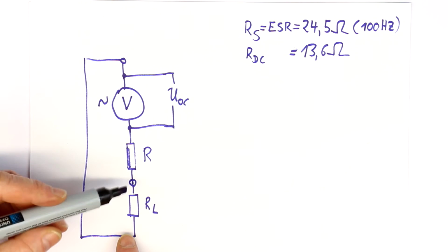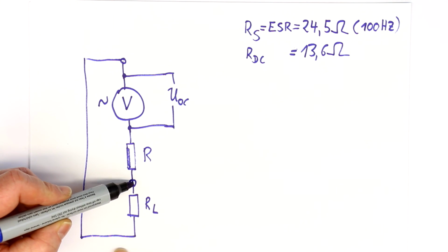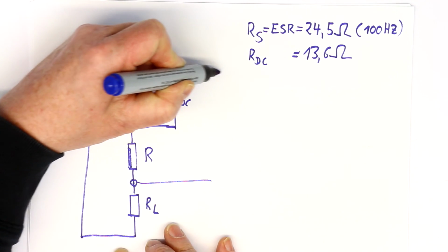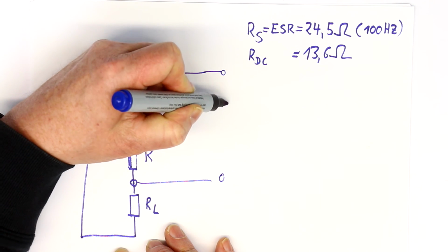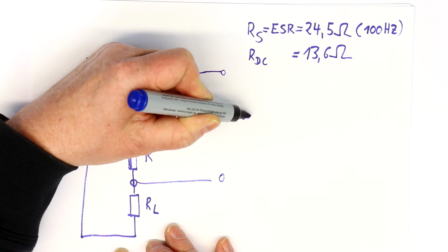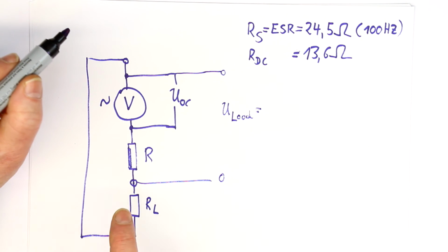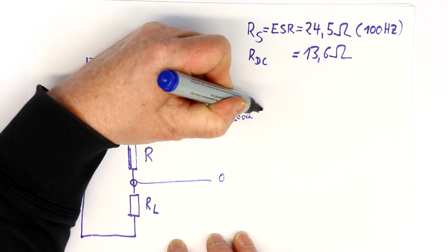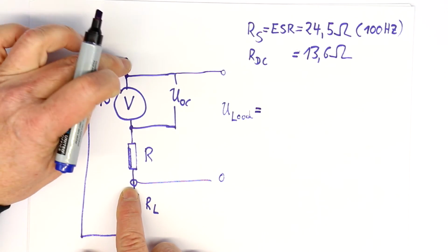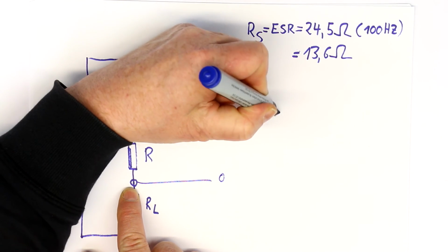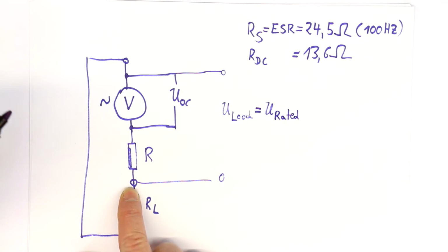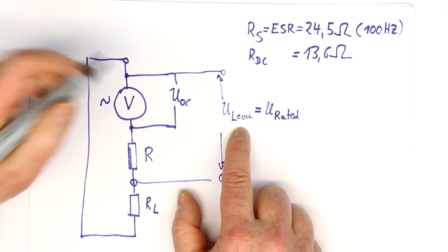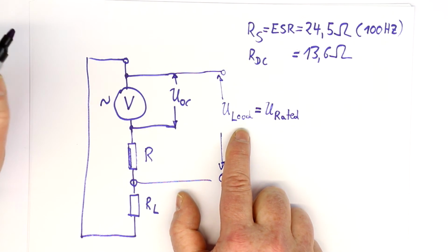And of course, if we put a load on the output terminals, then we get a voltage divider, and now we would measure the voltage under load. And if our load is the maximum allowed resistance, or the maximum allowed load, then the voltage here at the terminals will drop to the rated voltage. Aha, well, now we have something that we can do some calculation with.